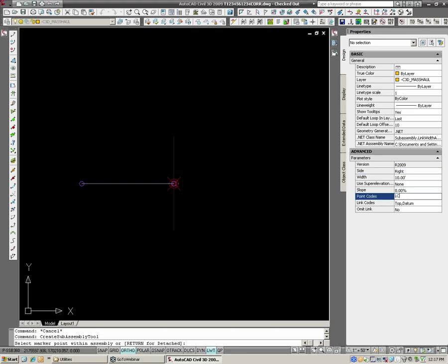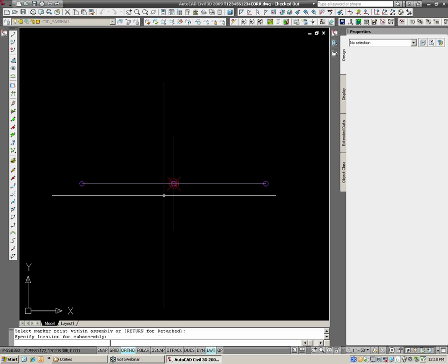Do LC. Okay? And you can really name this whatever you want. Keep the point code name simple, though. Don't make a big, huge name with a bunch of spaces. Just keep it a couple letters, 3, 4, no spaces in it, and you'll be in good shape. So now, since I changed it to the right side, it's going to attach on the right side. Okay? So we're done with that.